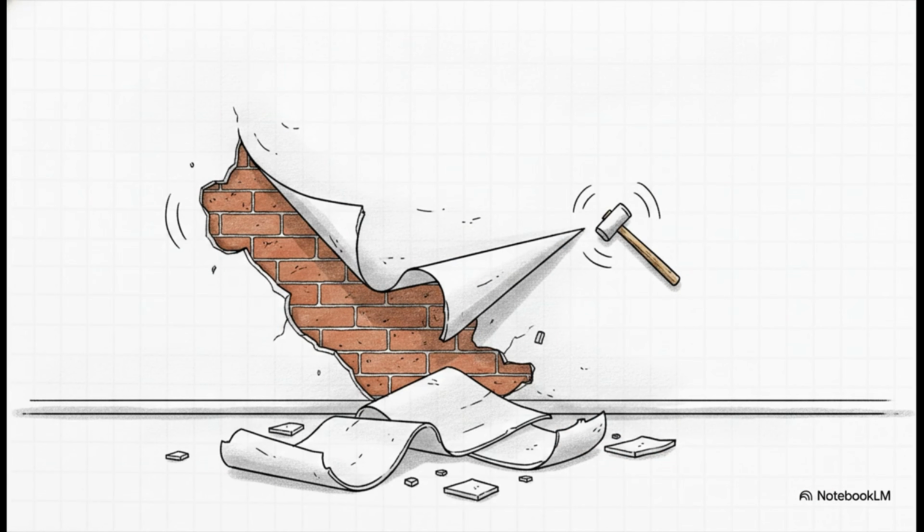But the ultimate catastrophic failure is the total loss of adhesion, complete bond failure. If you skip curing the masonry, or forget to rake the joints, or ignore hacking the RCC faces, the plaster simply won't bond. You're going to catch this during checking as hollow-sounding patches when you tap the wall, which eventually leads to substantial flaking and peeling, and the only way to fix it: scraping it entirely off and starting over. That is a massive, totally avoidable blow to your project budget.